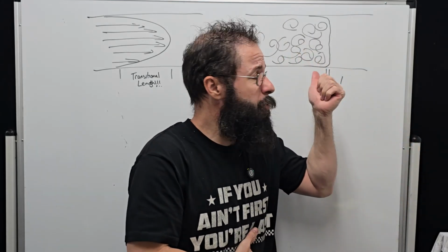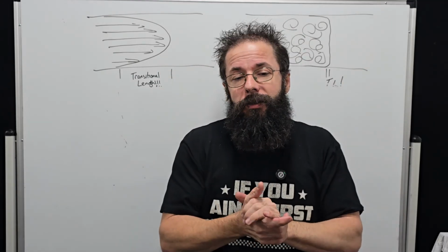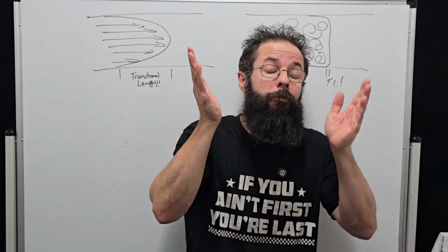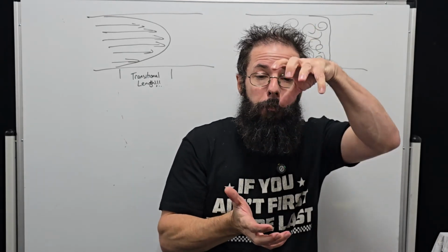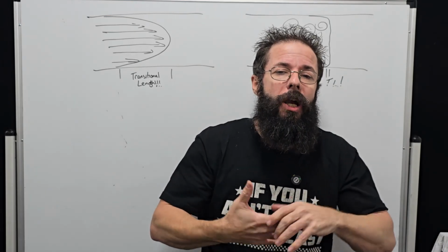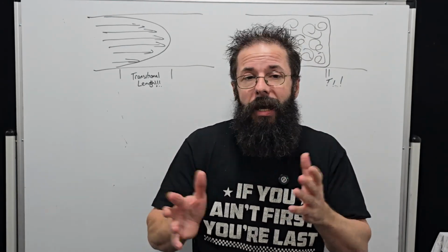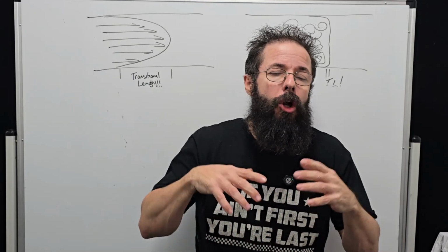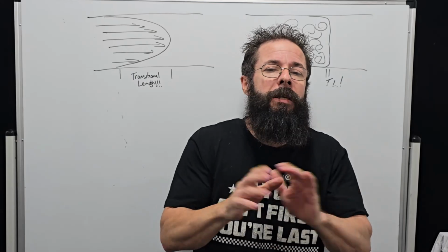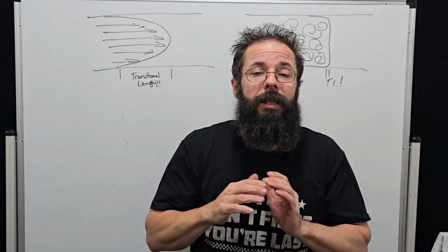But this is what I wanted to cover and explain, that the eddies aren't half the size of the pipe or so on. They can be, again, if we have really, really bad valve guides and port angles. Yes, they will be behind the valve guide, but again, some decent shaping will eliminate most of this, because I've seen some comments saying, oh, you're always going to have pockets with a poppet valve. That's not true. If you learn how to shape ports and do it right, you can minimize all this to having very, very small dead areas, almost eliminating them all.